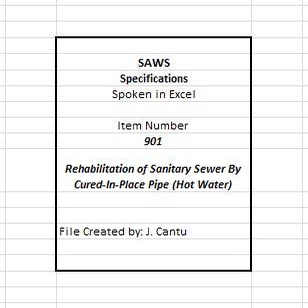A percentage of the instantaneous flexural modulus value, as measured by ASTM D790 testing, will be used in design calculations for external buckling. The percentage, or the long-term creep retention value utilized, will be verified by this testing. Values in excess of 50% will not be applied unless substantiated by qualified third-party test data. The materials utilized for the contracted project shall be of a quality equal to or better than the materials used in the long-term test with respect to the initial flexural modulus used in design.